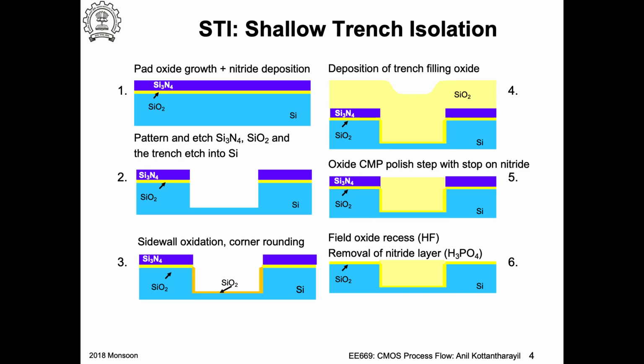Okay. So if I use any other etch process, for example, if I use a wet etch process, it will etch from everywhere. And if I expose it to a plasma for etching silicon dioxide, it would etch the silicon dioxide vertically from everywhere. Okay. But if I use a CMP, this is actually doing a polishing. So once the surface is smooth, it would not etch much. Okay. So that is the idea, or you can stop the etching. So the CMP will be done, and the silicon nitride is used as an etch stop for the CMP process. Okay, so that is where the chemical component in the CMP comes into play, and you get a flat surface.